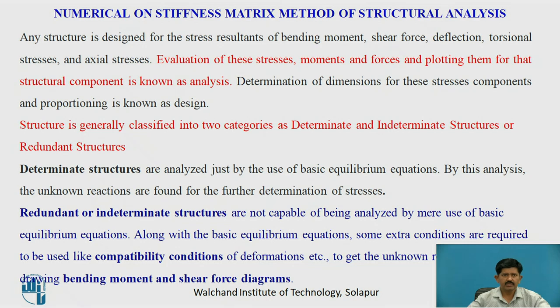Now, any structure is designed for the stress resultants of bending moment, shear force, deflection, torsional stress and axial stress. The evaluation of these values, or these moments and forces, and plotting them for the structural component is known as analysis. And the determination of the dimension for the structural component and proportioning is known as design.